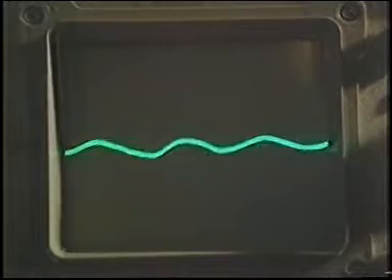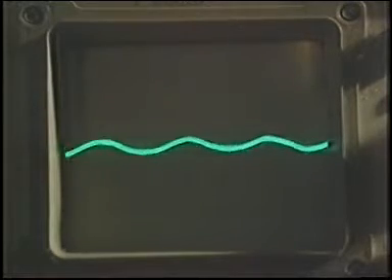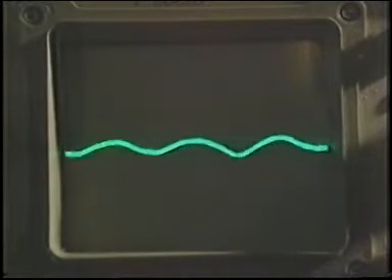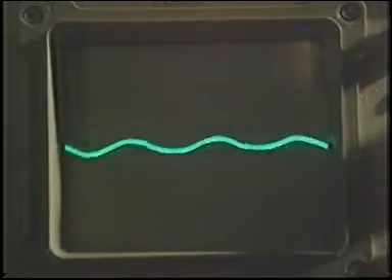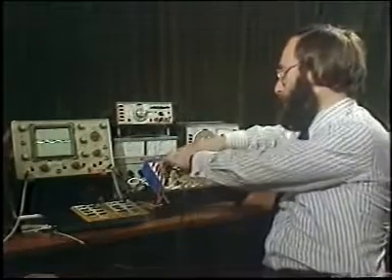Well, it's beginning to look pretty respectable now. It's looking almost like a sine wave. You can see a bit of low-frequency noise still perturbing the signal, and we could get rid of that by putting in some high-pass filtering right down at the bottom end to block out some of the low-frequency noise components. But we shan't be doing that for the moment. However, I think you'll agree that by doing a bit of signal conditioning, you can certainly make a big difference to a signal. And just to remind you, let's go back to where we came in.